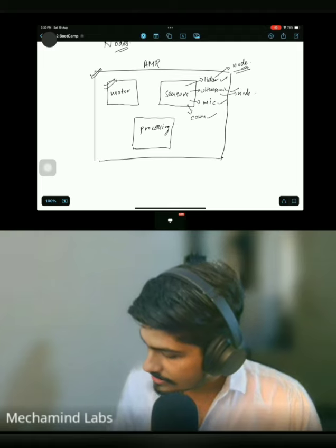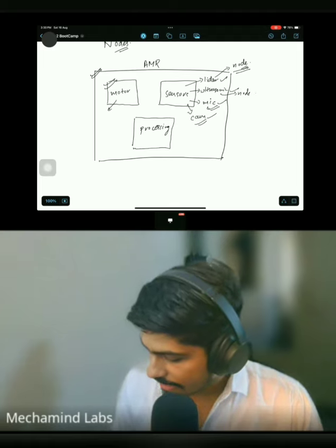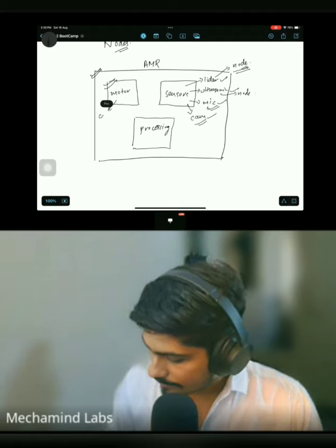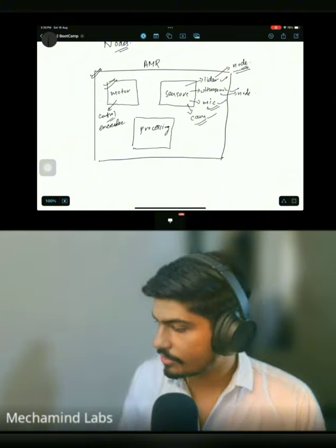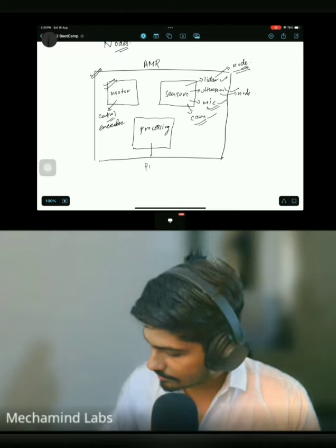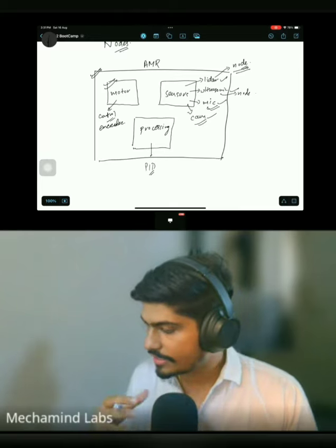So I have multiple nodes inside a package. A camera node, and for motors I'll have a motor control node, which will control the motors. I'll have an encoder node, for example, which captures data from my encoder and gives it to me. In the processing section I will have, for example, a PID node which is doing all the PID calculations at the backend.